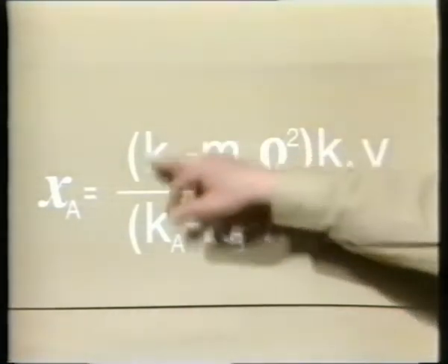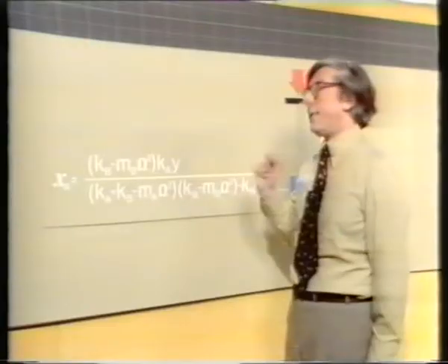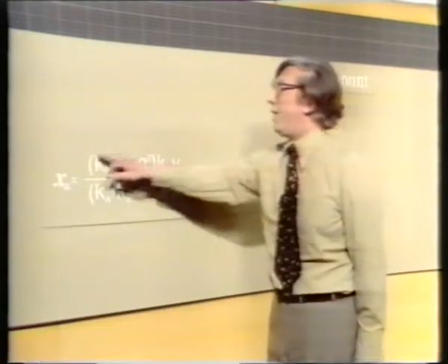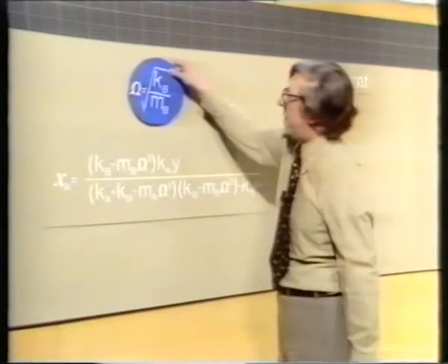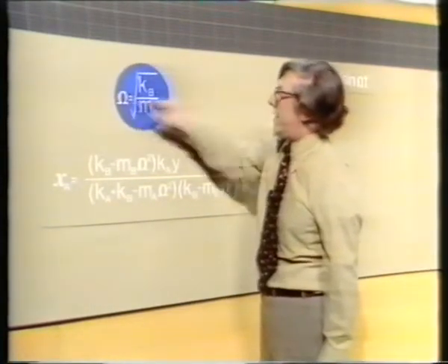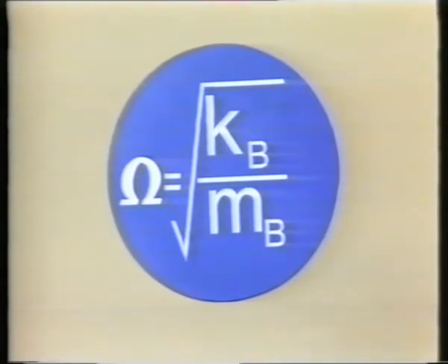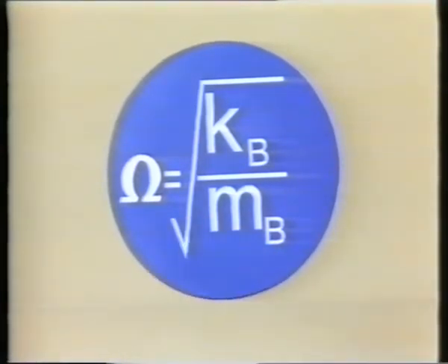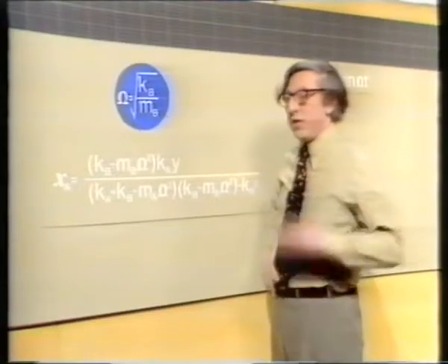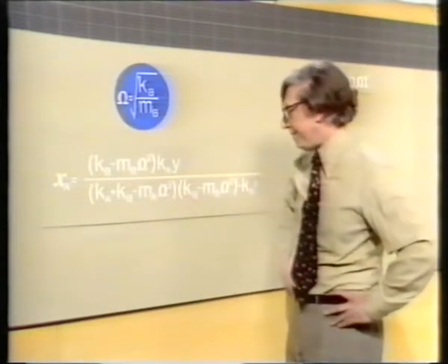So we've got to look at the bracket. And that's the condition for vanishing, if the bracket vanishes. And that will happen when this is satisfied. And that really gives me the parameters of the vibration absorber in terms of the given forcing frequency. And that's a rather simple, interesting result.